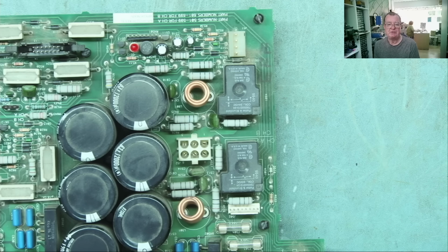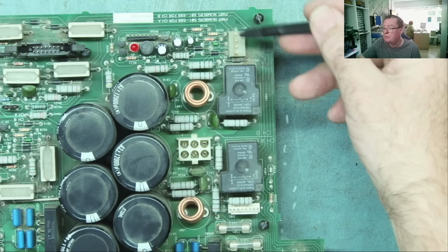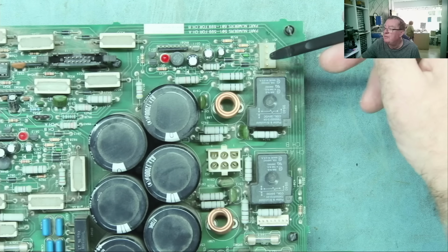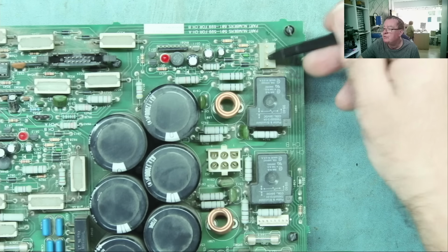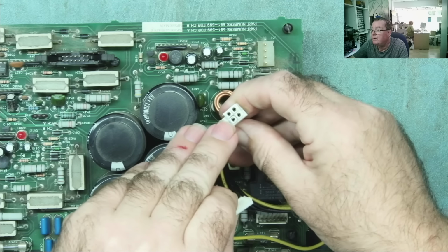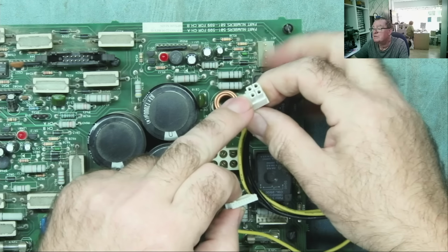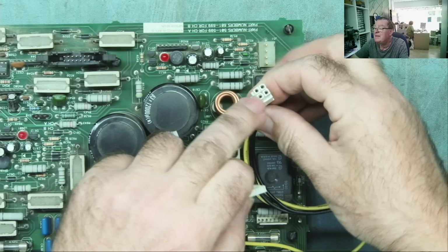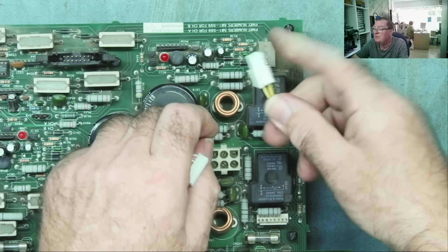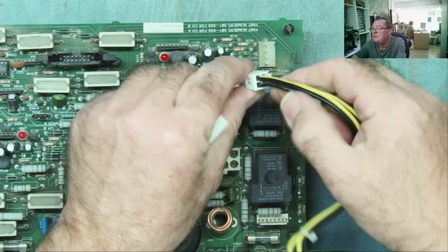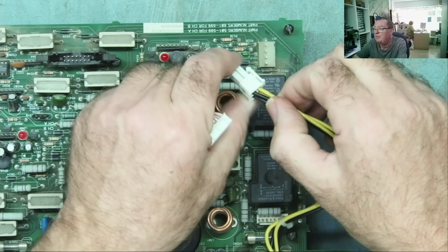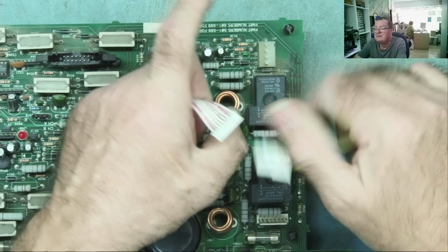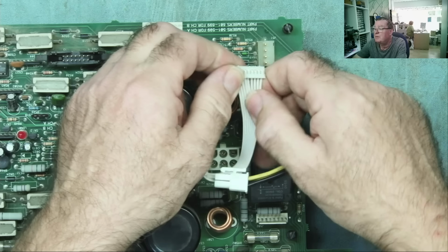So switches, yeah. Connectors also have physical connections. They're connectors, yeah. Quite often the problem can be in the other part that fits onto there. So basically a problem here, usually again where there's quite a bit of current going down and it starts to arc and it'll blacken the connector. The only real way to fix this, if you can't replace the thing, you need the tools to extract it and clean it properly. Don't think you're going to do this easily with switch or contact cleaner, or replace this if you can, yeah.